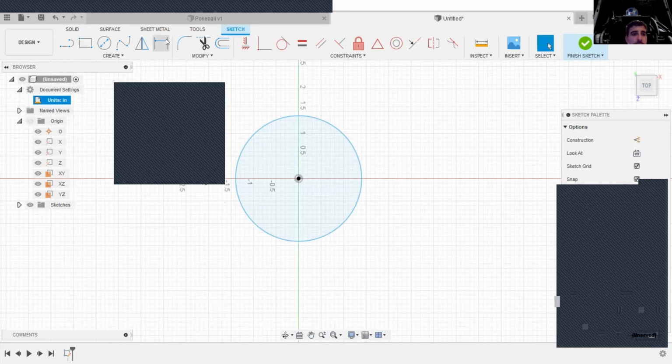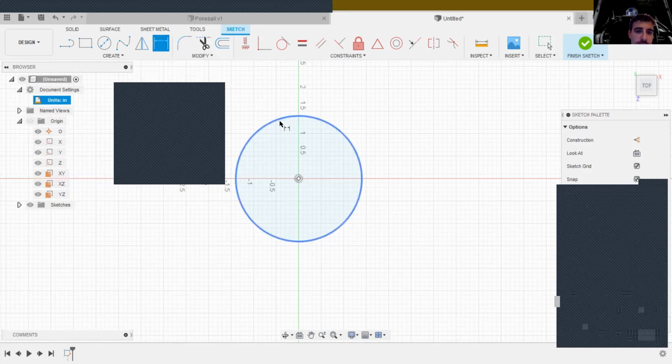And then, by the way, that was another thing I want to touch up on. Thank you for reminding me, Maria, is the sketch dimension. This allows you to set a specific dimension to everything. So I just clicked the outer circle and it's asking me for the diameter, which I want at 2.8, and I'm going to leave it at 2.8. And it's an easy adjustment tool.